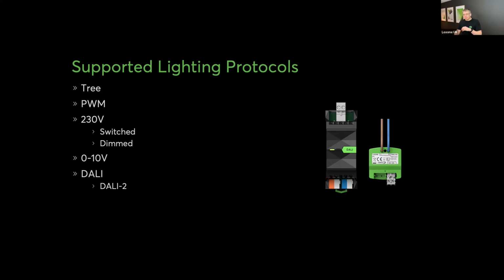At the moment, DALI 2 is only supported by DALI Air, which is great for retrofitting, but also commercial applications where you might have such a long run that having a DALI Air may make more sense, because you can have them out in the field. But the DALI extension will support DALI 2 within the next 2-3 months. All existing DALI extensions will receive a firmware update to support DALI 2.